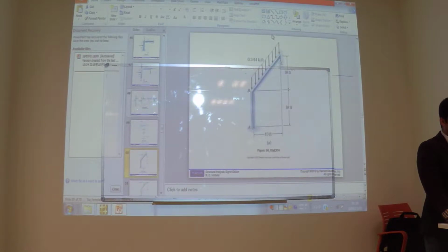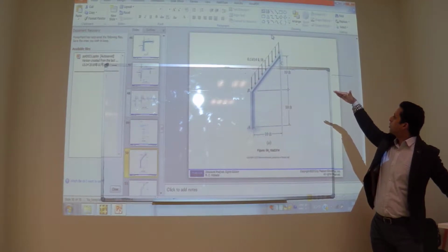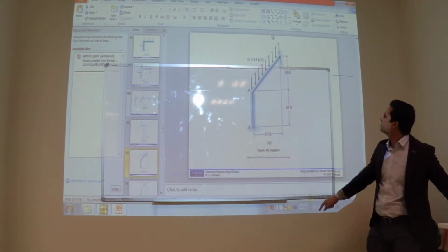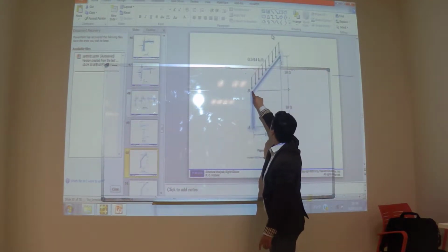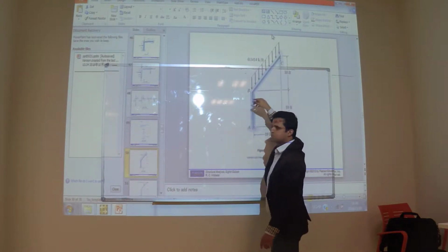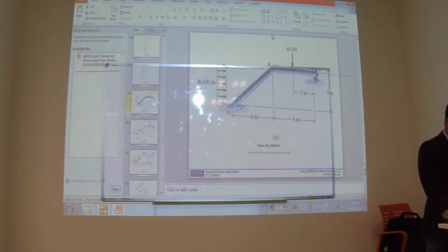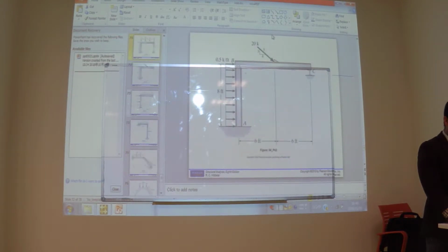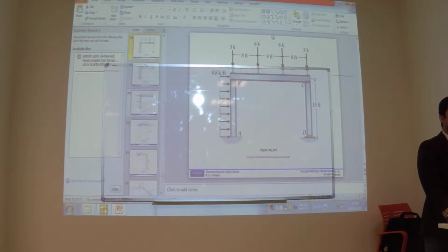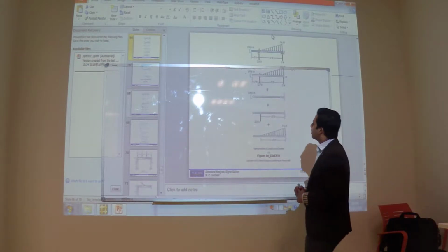This example is also similar. There is no difference. You only have to make this load perpendicular to this member by taking the cos of this angle. If you take the cos of this angle, you will get two loads: one horizontal load like this, another vertical load. That is the only difference, nothing else. How do we draw it? With the slope. Same, draw it horizontal and vertical.